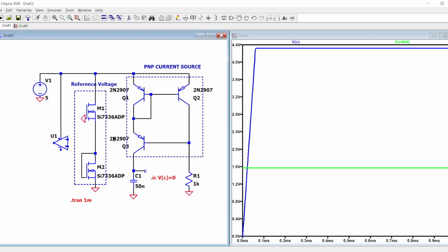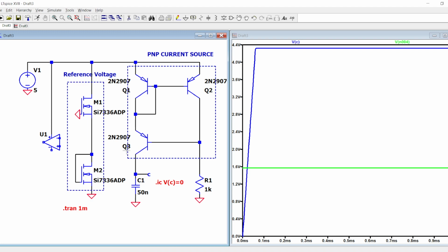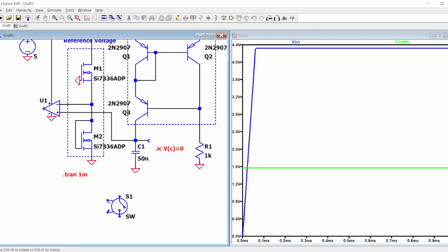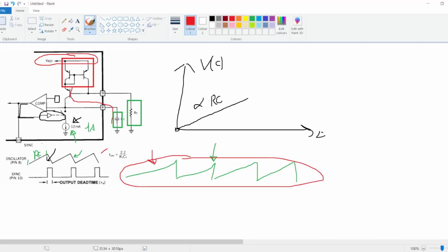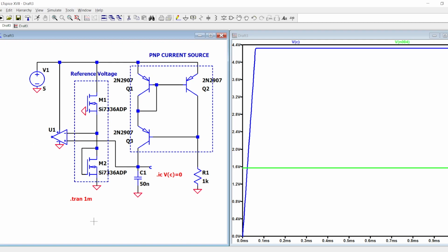So now the circuit is more realistic because we are just using op-amps and MOSFETs. We need to take the positive voltage of this guy here, and then we say when the positive voltage is higher than the threshold voltage, which is this, we have to reset this guy here. We can either put a switch with a current source, or we can put another MOSFET. I'd rather say that in this case, just for simulation purposes, just put another MOSFET and design a feedback network